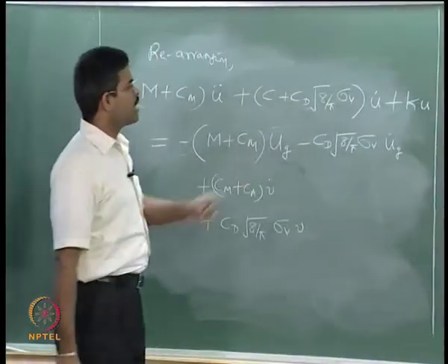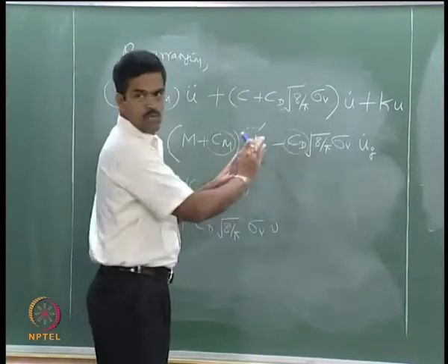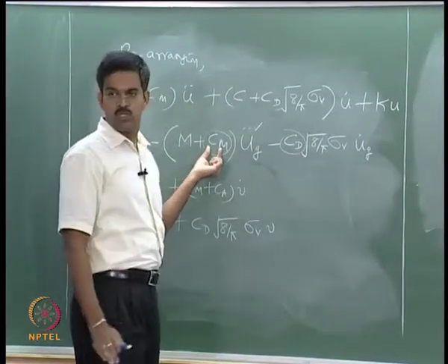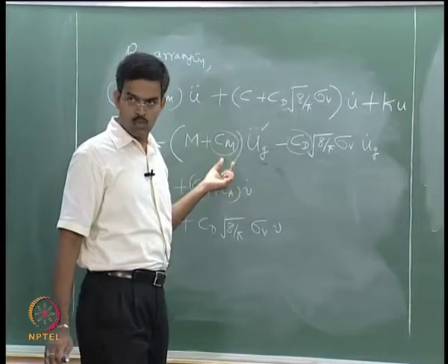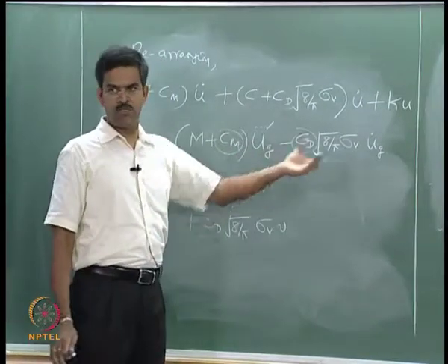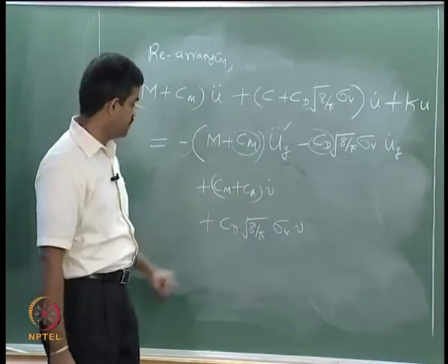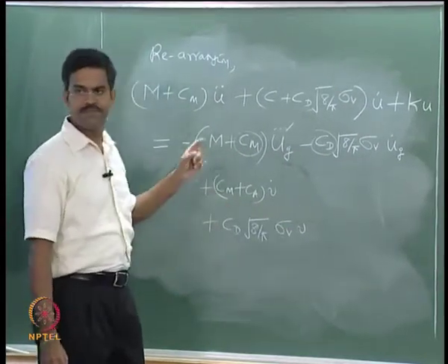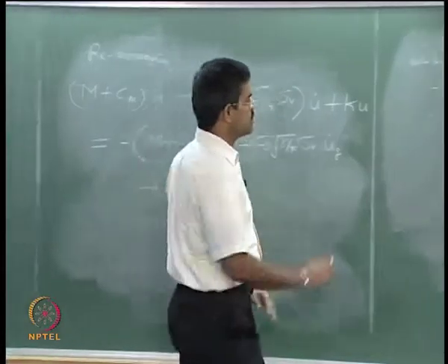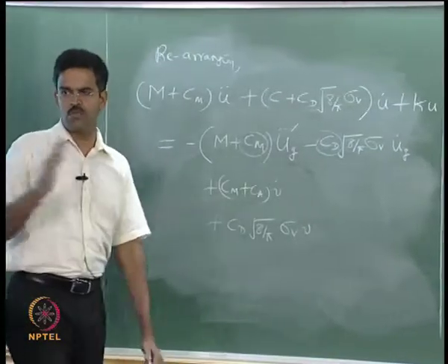So, let us see this equation back again. I have this with me. Of course, CD and Cm are known to me, we know this. There are various international codes, API for example, which will advise me what CD and Cm I should use for a depth variation, or what approximate values I should use for a specific sea state. So, CD and Cm are known to me, Ca is also known, and it is a linearized drag, I know this. What I will solve for is u, which is actually the displacement of the cylinder.